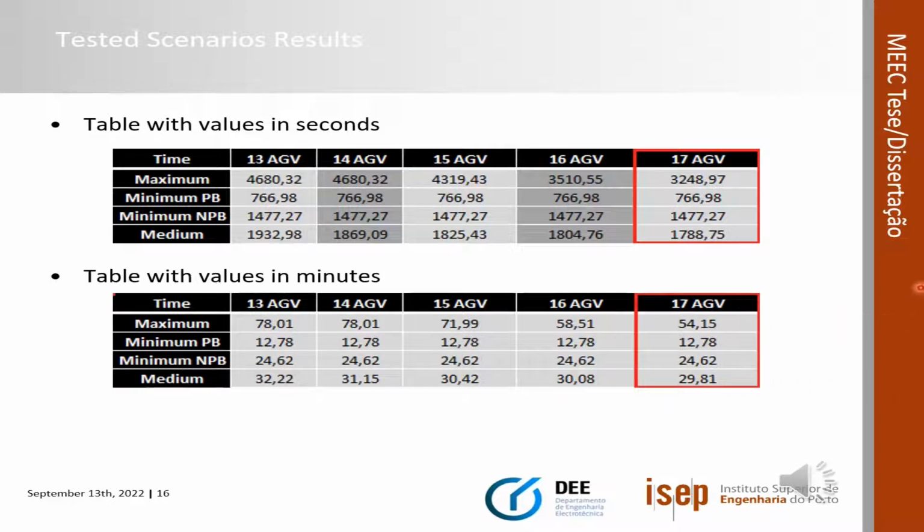It is also important to mention that part of this time is due to the journey of the AGV itself, between the stand and the terminal. The time varies depending on the stand where the baggages are located. Since, if you go to the first stand, the AGV will be loaded for longer than if it goes to the last stand. For example, if the trip takes place at the first stand, the AGV will lose an average of 10.5 minutes for the trip, while if it is on the last stand, the AGV will lose approximately 9 minutes in travel. This is due to the difference in speeds between the AGV being loaded and unloaded.